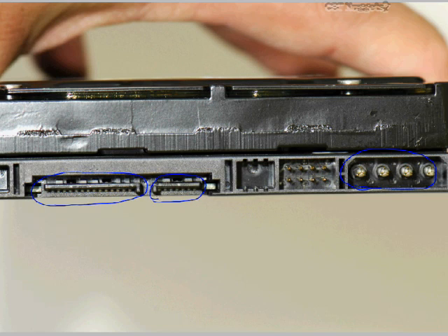I find that serial ATA connectors and power connectors very often come unplugged or get jostled loose. Some serial ATA data cables also have a little interlock on them where it will snap into place, and you have to push down on them using your thumb to disengage them and then remove them. But otherwise, most of them have no such locking capability.